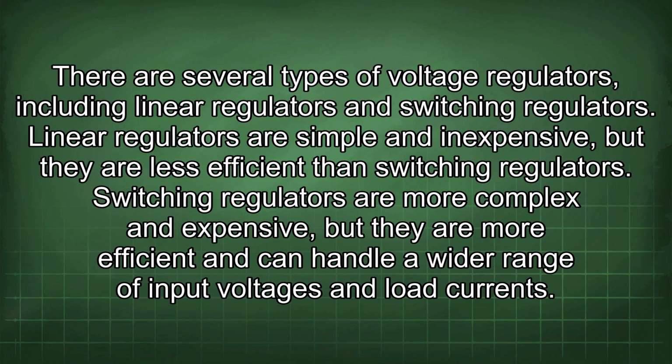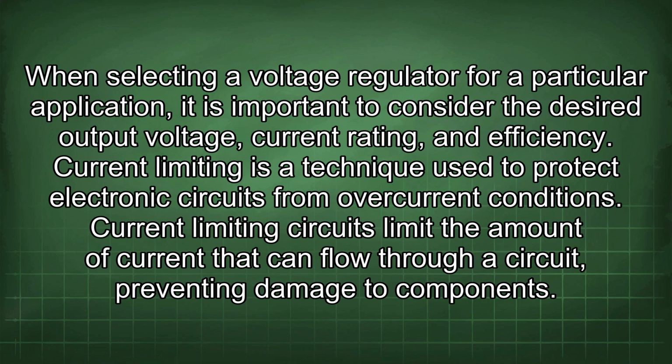There are several types of voltage regulators, including linear regulators and switching regulators. Linear regulators are simple and inexpensive, but they are less efficient than switching regulators. Switching regulators are more complex and expensive, but they are more efficient and can handle a wider range of input voltages and load currents. When selecting a voltage regulator for a particular application, it is important to consider the desired output voltage, current rating, and efficiency.